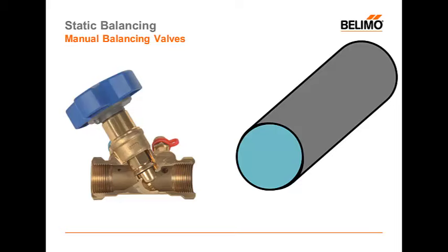There is a small obstruction and there is some pressure loss just from having a fully open balancing valve in the loop, but it's not appreciable, and so we'll estimate it as being an unobstructed pipe. When the system is balanced, the balancing valve is closed, and as the balancing valve gets further and further away from the open position, it creates a smaller area through which the same amount of water needs to pass. And this is what creates your pressure loss.